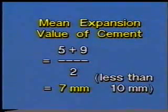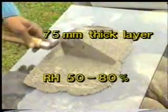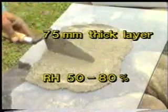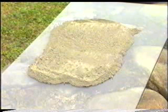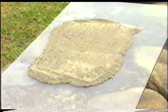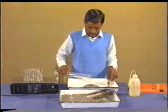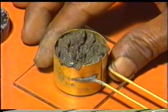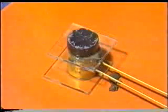In the case of unsound cement, the aerated cement test is carried out, which involves spreading out the cement in a 75 millimeter thick layer in an atmosphere of relative humidity of 50 to 80%, maintaining a temperature of 27 plus or minus 3 degrees Celsius and keeping it for 7 days. Retest this aerated cement sample.